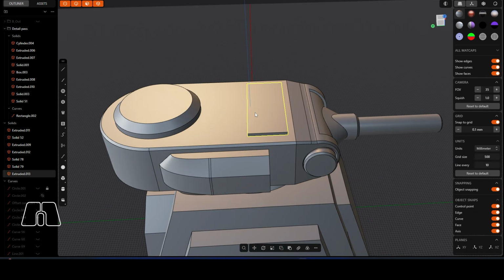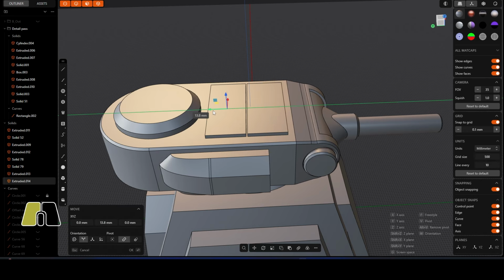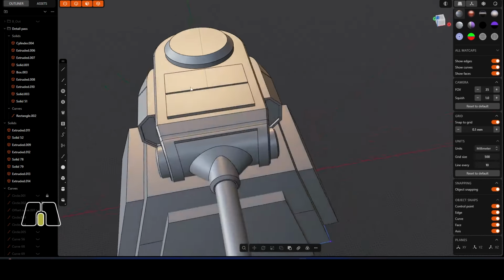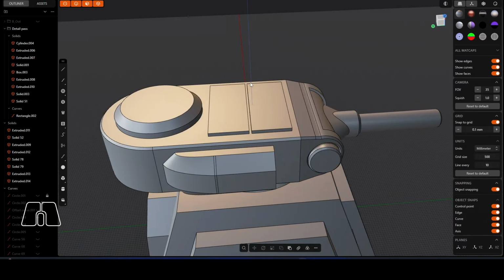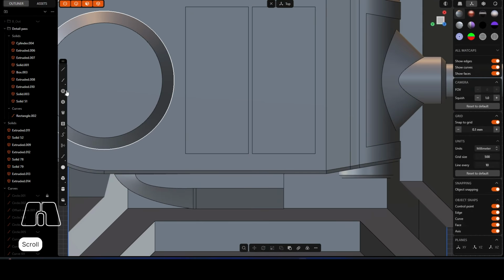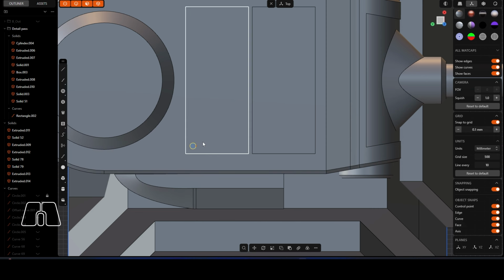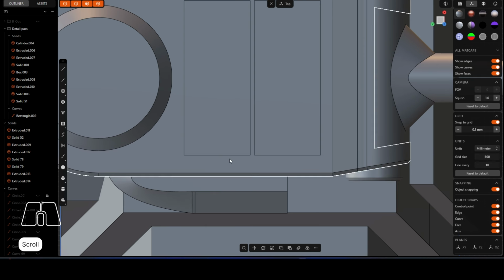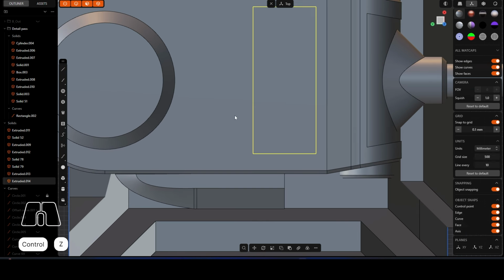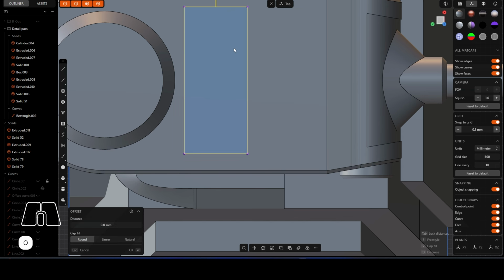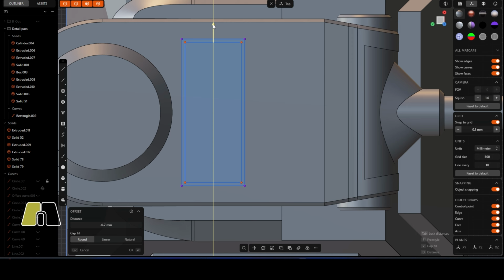When you get into the smaller parts, it's always good to duplicate the smaller, more intricate bits of detail. So maybe that's a bit of armor there. Could also maybe create some screw stamps in here. So what we could do is go back there for a second, let's just get rid of that. There we go. So get rid of this one. What we'll do is use O, just inset that, make sure it's linear so it doesn't curve it. So let's just grab that again to something like that.